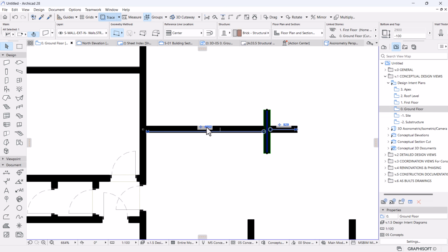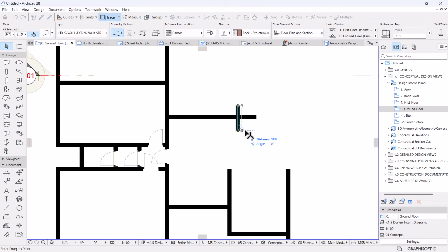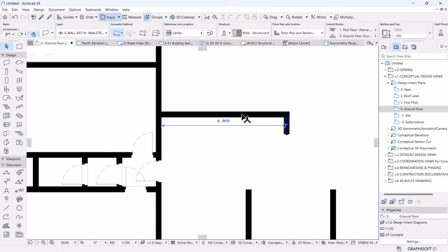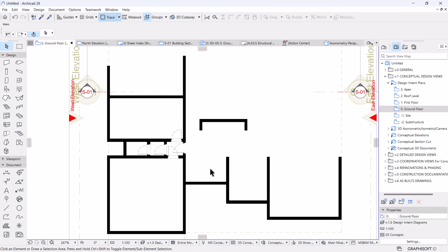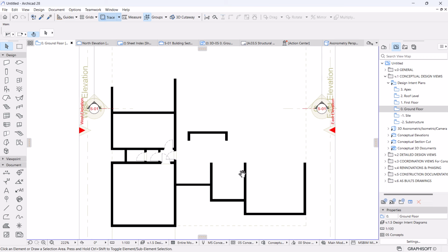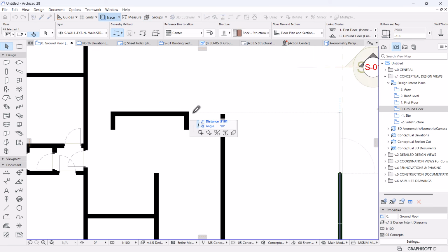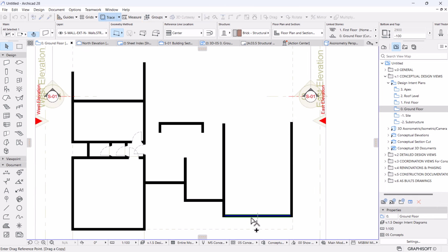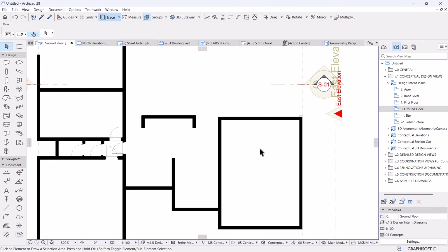Okay, and then from this side, let's keep it at 4 meters. It has to be somewhere right in the middle of the staircase. So maybe chamfer it like that for now, and then I'll mirror a copy to the side, then this side will be the size of an opening, so 1.2 will suffice. Then I'll trim it off this side. Perfect. So I have my entry lobby, foyer, staircase. So this will be aligned with my family room space. So I'm going to copy this to the other side like that and chamfer these ones.